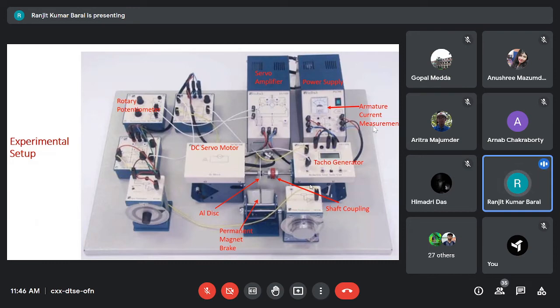So acceleration is the most fundamental mechanical quantity, a motion variable. With respect to time, this acceleration gets integrated and gives rise to velocity, and with respect to time, velocity gets integrated and gives rise to displacement. So here, as these two torques, load torque and generated electromagnetic torque, are balanced, there will be no further acceleration, and the rotation will settle down at a steady speed.